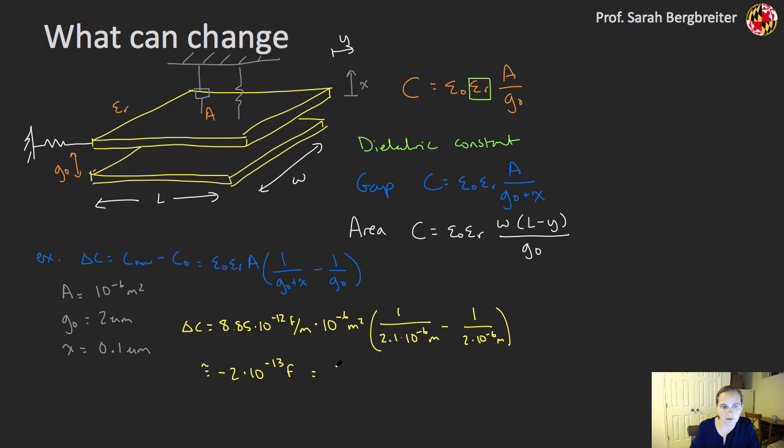approximately -200 femtofarads. Or I could think of that as 0.2 picofarads. So that sounds pretty small, but there's a lot of capacitive electronics out there and interface circuits that we'll talk about that can pick up sub-femtofarad changes of capacitance. So you can do some really nice displacement sensors, for example, and ultimately inertial sensors with capacitance.